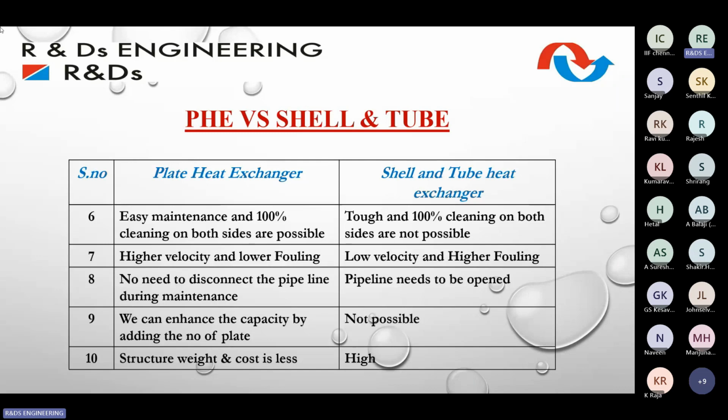They call it a primary condenser cooler, secondary condenser cooler, sub cooler, like that. Whereas if they are going with the plate heat exchanger, because of its less weight and compactness, the entire structure itself becomes very small, and the structure cost also will be very low compared to the shell and tube heat exchanger structure. So these are the major advantages of the plate heat exchanger.